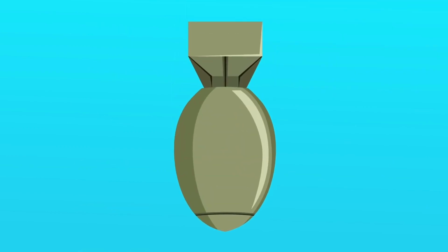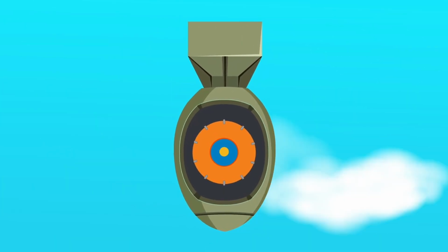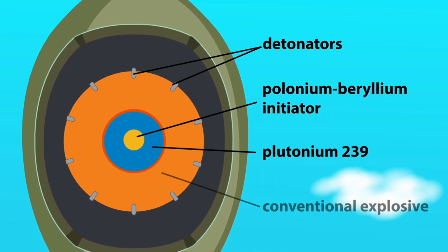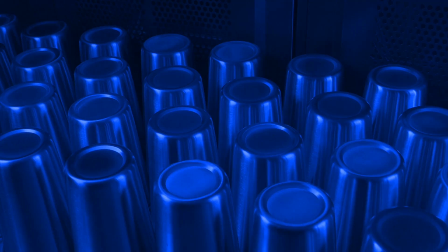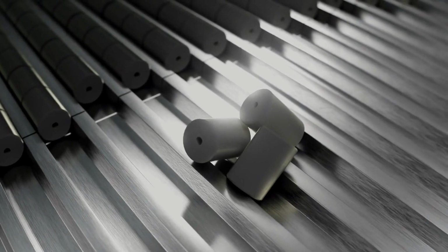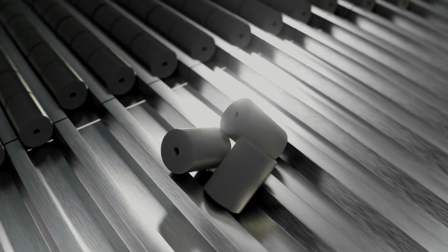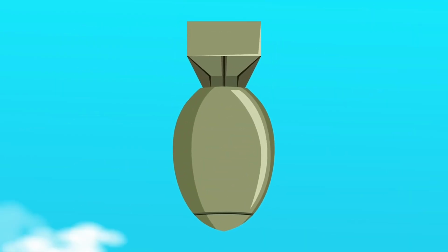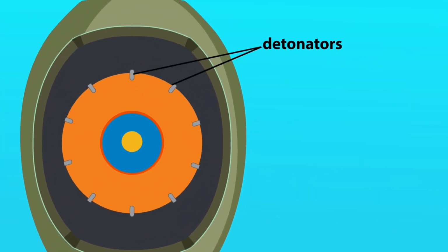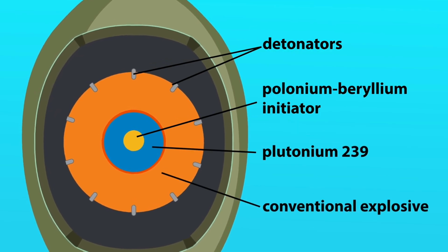A nuclear reactor, the heart of a nuclear power plant, comprises several critical components designed to initiate, maintain, and control the fission process. Fuel rods. These rods contain the fissile material, typically uranium-235 or plutonium-239. The fuel is often formed into ceramic pellets and stacked into metal tubes, which are bundled together to form fuel assemblies. Control rods. Made of materials like boron, cadmium, or hafnium, control rods absorb neutrons and regulate the fission process.